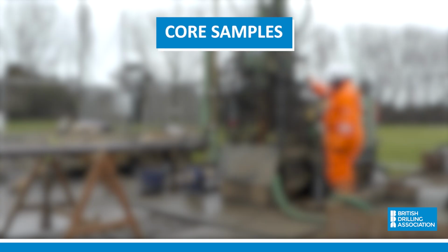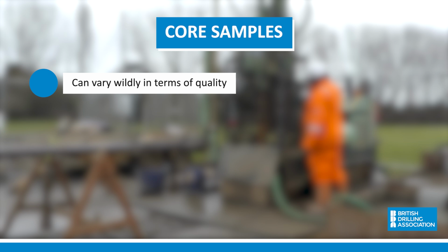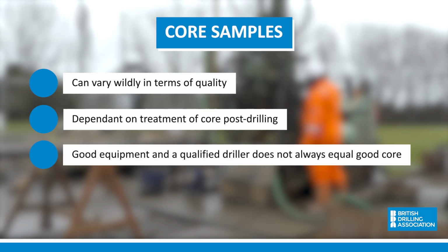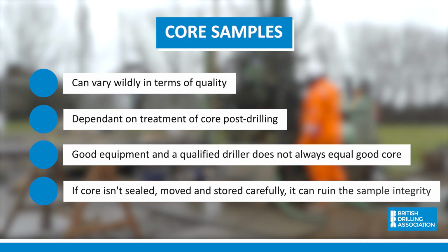Core samples achieved through rotary coring and sonic drilling can vary wildly in terms of quality, and it is as much dependent on their treatment post-drilling as it is about the skill level of the driller or the method of drilling. A driller can use the best equipment on the market and have 25 years experience, but if the recovered core is slammed into core boxes, uncapped and unprotected from the elements, they may as well have not bothered.